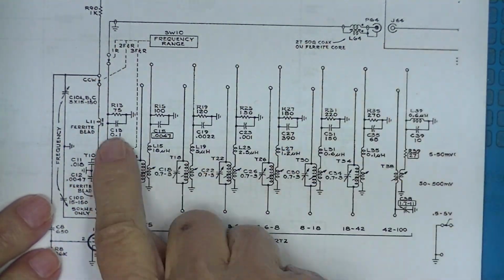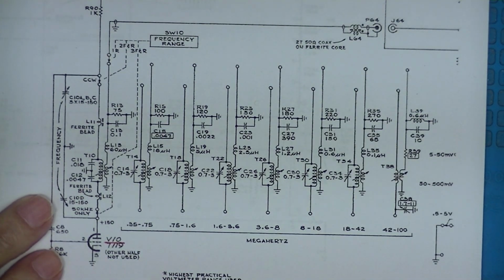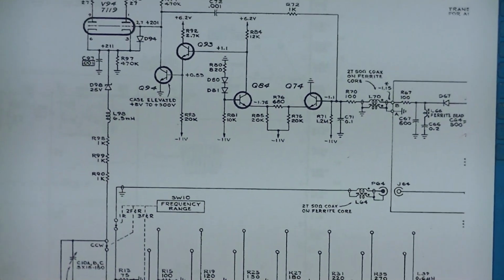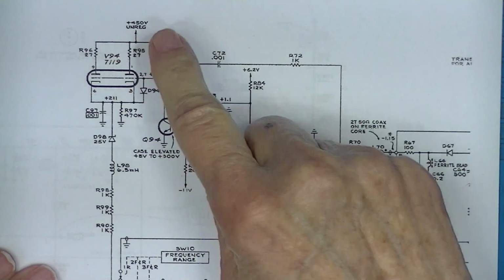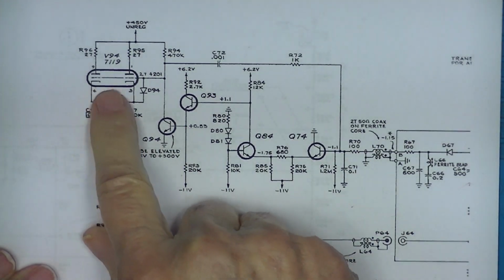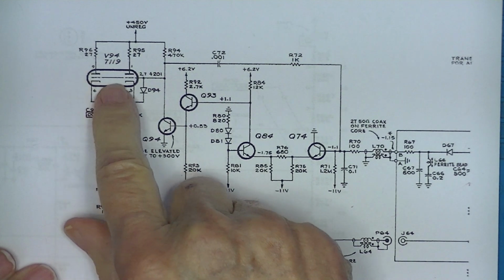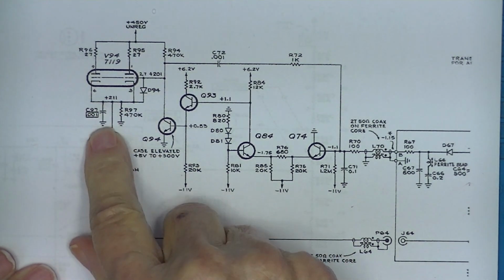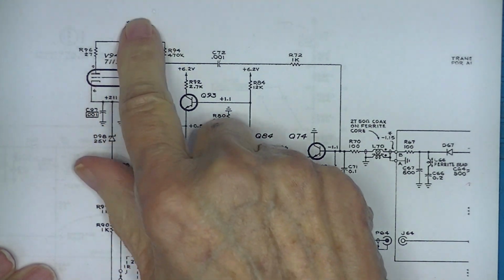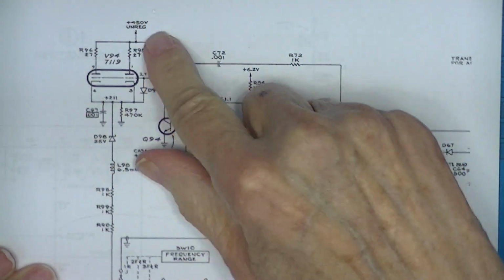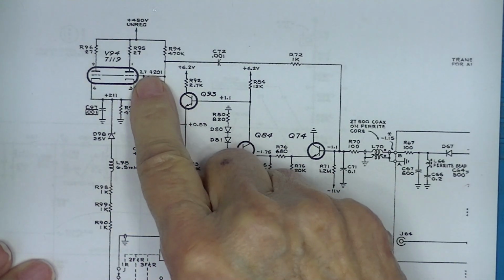Remember that the output of this oscillator, which is right here, is dependent upon the voltage supplied here, which is shown here as being 150 volts. That's not always the case. Here is the other vacuum tube. 450 volt supply is only furnished one place, and that's here. These two triodes are essentially in parallel with each other. Grids are connected together. Cathodes are connected together. And the plates are connected together with current equalizing resistors. This acts as a variable resistor. The resistance of the circuit varies with the voltage applied here.